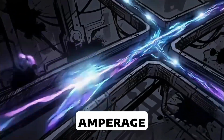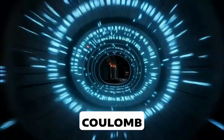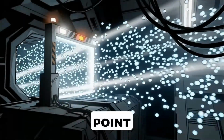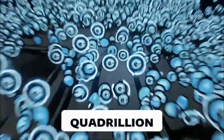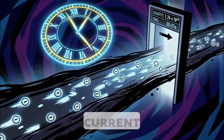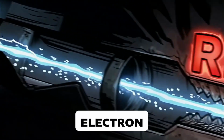Current, or amperage, is the rate of electron flow. The symbol is I, and the unit is the ampere, or amp. The chapter defines 1 coulomb as a quantity of charge, and when 1 coulomb of electrons passes a point in 1 second, the current is 1 ampere. 1 coulomb contains about 628 quadrillion electrons. That number is huge, but it matters because current is measured by the quantity of electrons moving past a point over time. Resistance is opposition to electron flow.